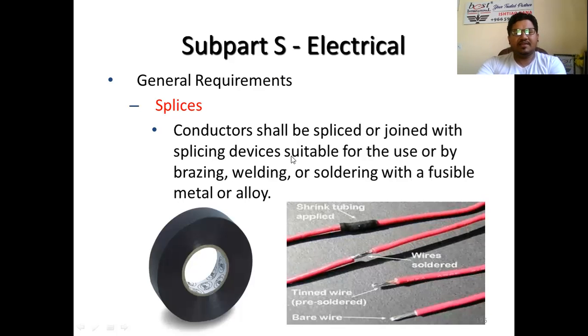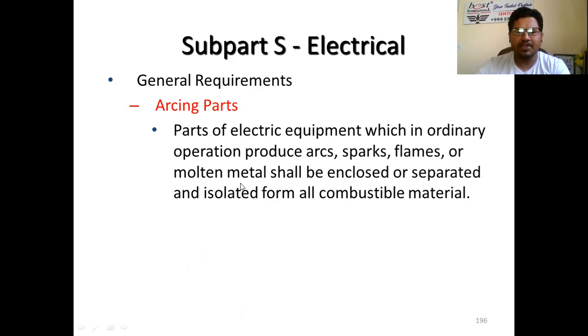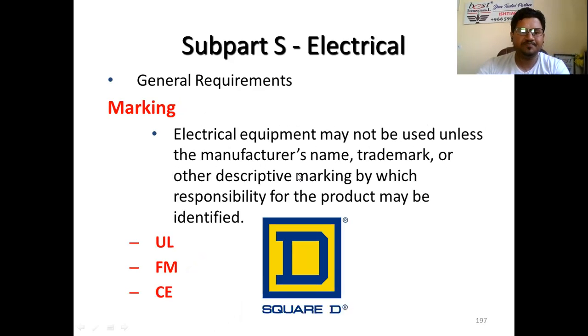Okay, the splices, like the conductors, shall be joined with splicing devices suitable for the use, or by brazing, welding, or soldering with a fusible metal or alloy. Arcing parts, again, parts of electric equipment which in ordinary operations produce arcs, sparks, flames, or molten metals, shall be enclosed or separated and isolated from all combustible materials. So these are important safety instructions, or operational safety excellence, which need to be followed.